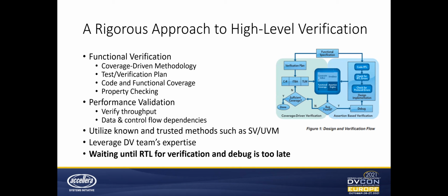Furthermore, at this level of design abstraction, you will likely encounter the need not just to verify the functional correctness of the design, but you'll also be expected to verify performance concerns, so throughput, latency, and that sort of thing. Even though we're focusing on the pre-HLS design instead of the RTL, we can still use known and trusted approaches to verification, such as SystemVerilog and UVM, allowing you to fully leverage your existing verification expertise.